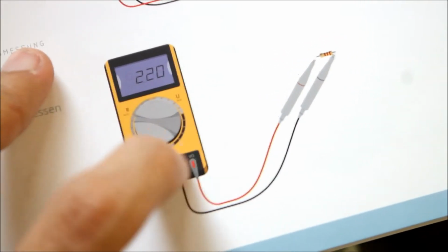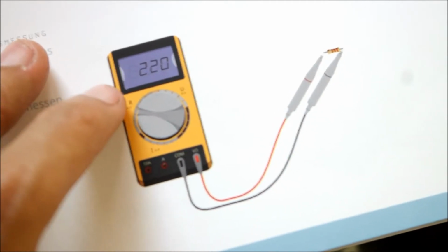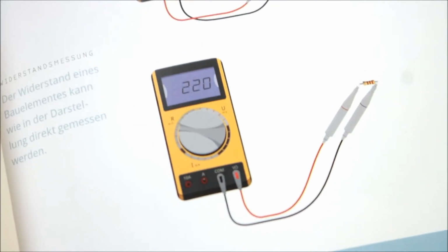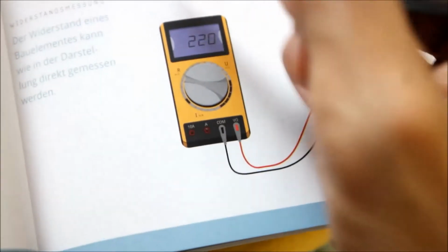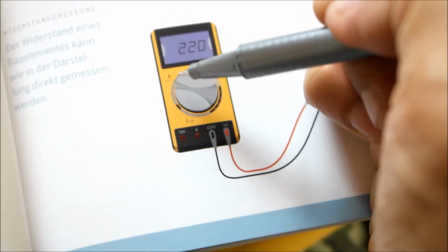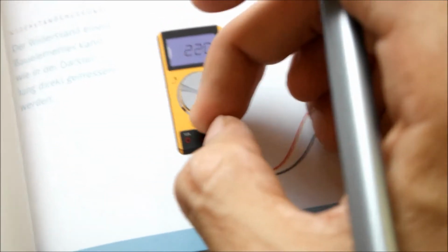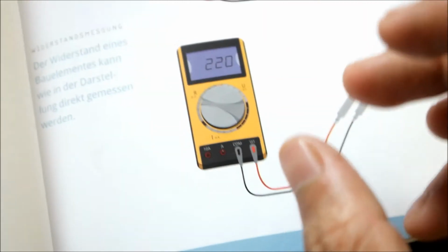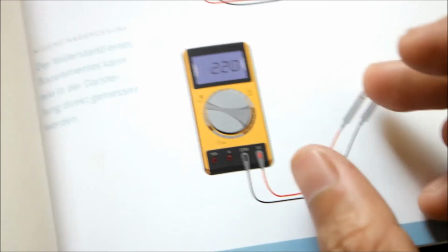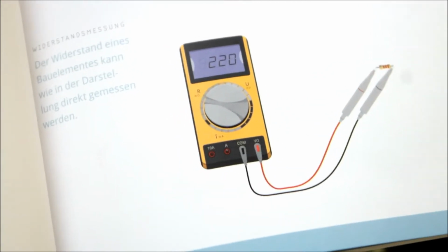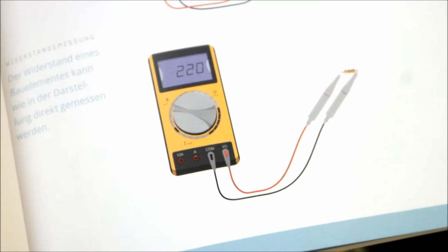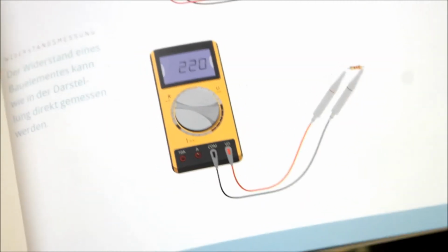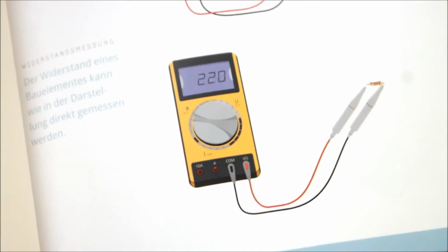It helps you a lot, and there's a central dial. I'm not quite sure if you are able to see that, but there is an R block here. This signifies the resistance. So rotate the arrow of the dial to R values, according to the expected resistance range. Say you have a resistor and you are not sure whether it's 100 ohms or 1 kilo ohm. There are certain ranges in the dial. Fix onto that and keep on checking.